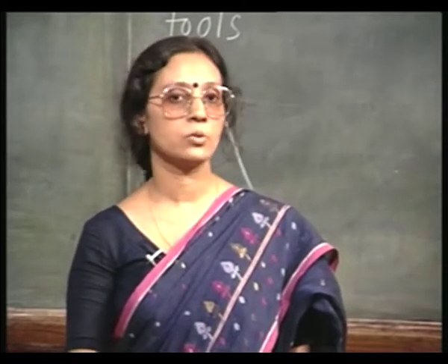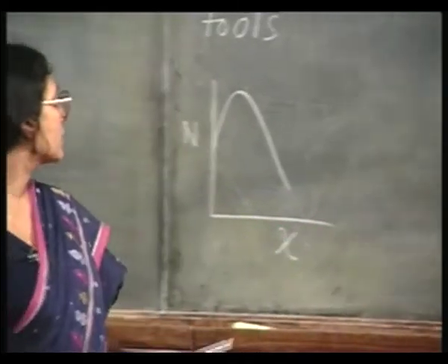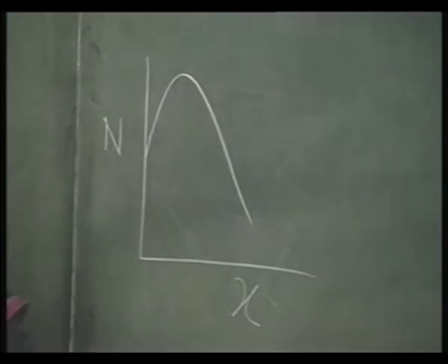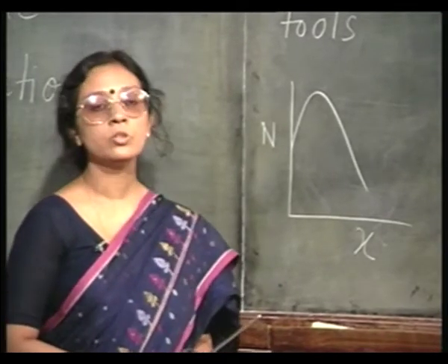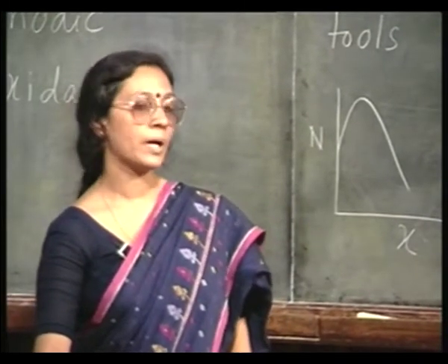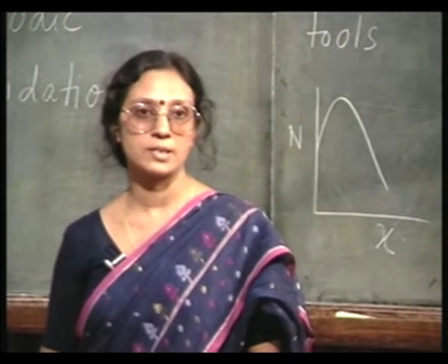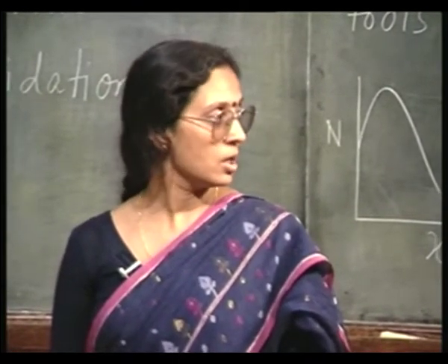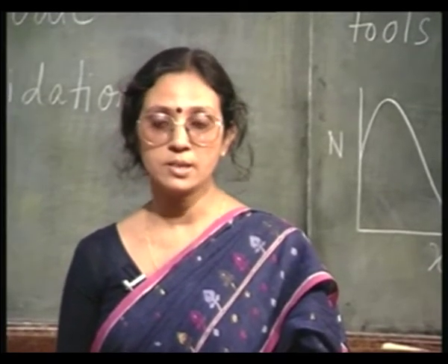So, the thickness of the oxide can be very accurately determined, and you can etch that oxide and measure the surface properties of the fresh surface thus exposed, and keep on continuing doing that in order to obtain the full doping profile. So, even though anodic oxidation is not really compatible with VLSI technology, it is not a standard processing step, thermal oxidation is the standard processing step, not the anodic oxidation. Still, it has its usefulness,